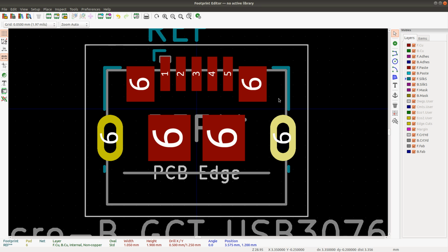Using that default footprint would never work for automatic component placement, because the component would just not go through the holes. I had to literally push it with my fingers really hard to make it fit. So that was not a working footprint. Let's see here.